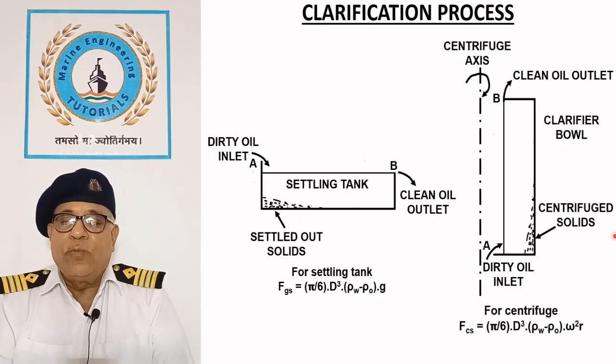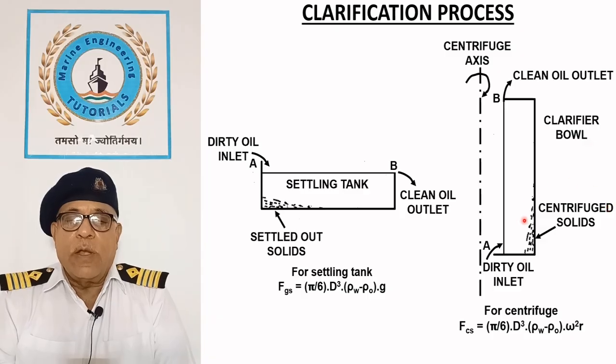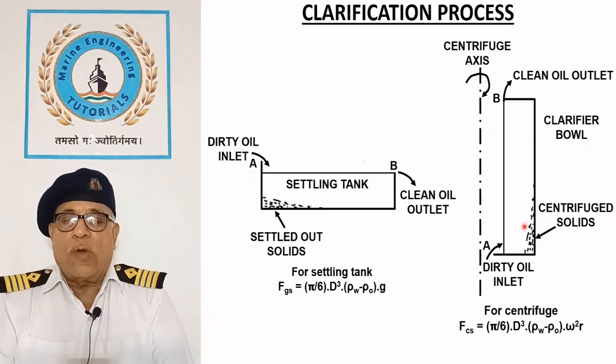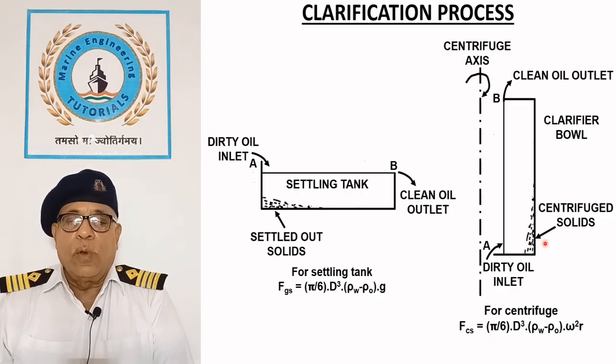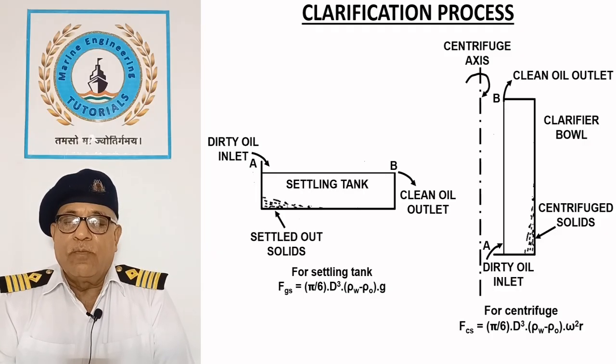Heavy solids are separated from oil and collected at the bowl periphery in accordance with the force of centrifugal separation, FCS. Solids may be removed separately and the process is called clarification. Oil which contains little or no water is treated in a clarifier bowl where the impurities and water collect at